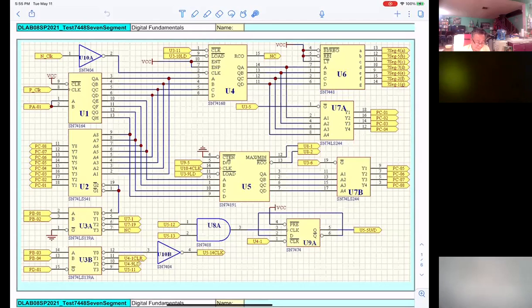Okay, so the first tab and the second tab, they write the data serial 5. Then it goes into the input of U2, a 541, which is just a buffer. If pin 19 and pin 1 are 0, then whatever is at the input will go to the output.